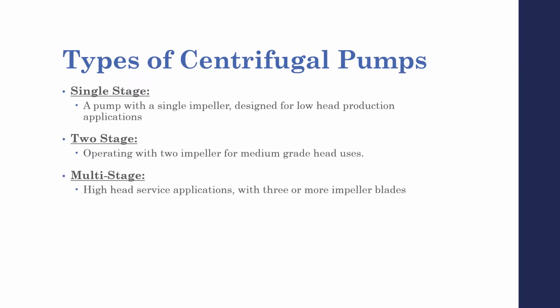There are a few different types of centrifugal pumps. There's a single stage, which is a pump that has a single impeller designed for low head production applications. It's a simple and easy design, with easy maintenance. It's ideal for large flow rates and low pressure installations.